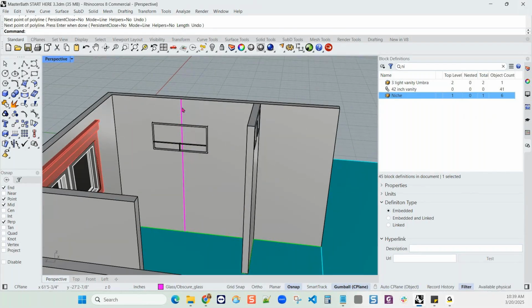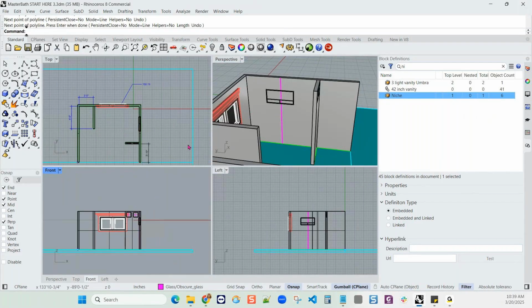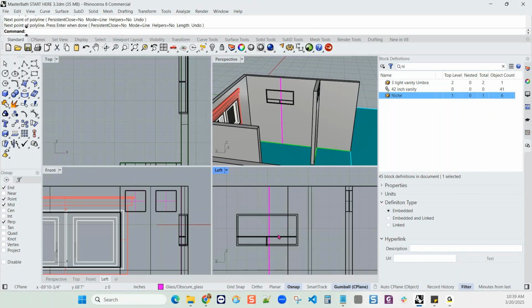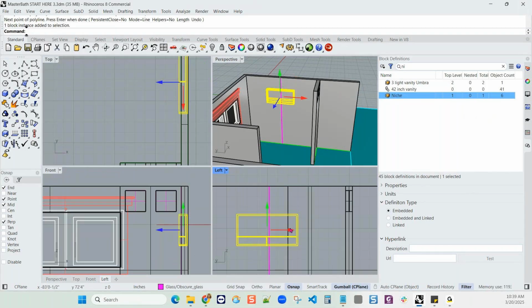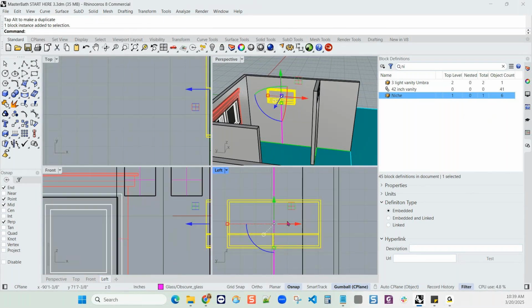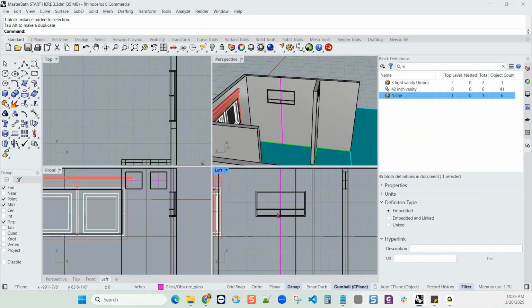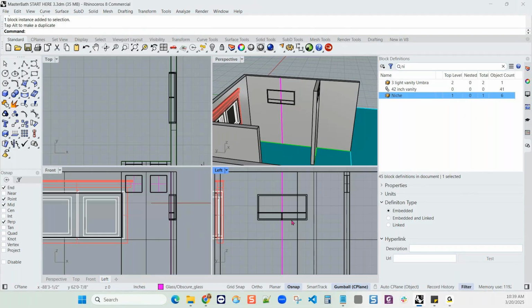And now that I have that, it's a little bit easier to line up, although Rhino can be as technical as you want to be. So if you want to give it the exact dimensions, it's happy to do it. Architecture within 1/4 of an inch they say is acceptable. I try to get within 1/8, but that looks good on that shower wall.